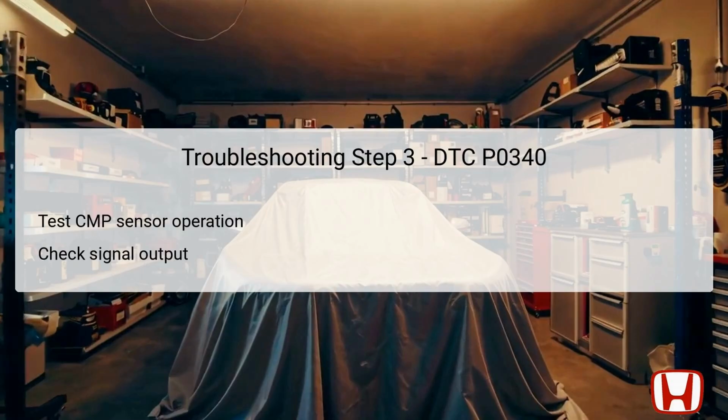In this step, the focus shifts towards testing the operation of the CMP sensor A itself. Utilizing a multimeter or oscilloscope, the technician should measure the output signal of the CMP sensor when the engine is running. The sensor should generate pulsing signals, reflecting its functionality and performance.